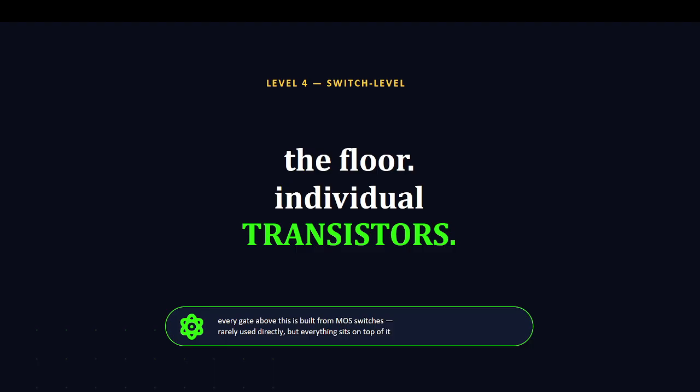Switch level modeling lets you describe hardware at exactly that resolution: individual transistors, individual switches. It's rarely used directly in day to day RTL design. Synthesis tools handle this layer for you, but it matters because every single gate you have ever used at every level above this is built from this.